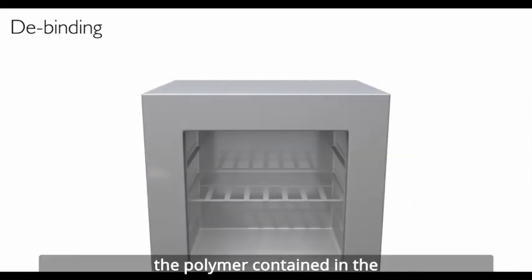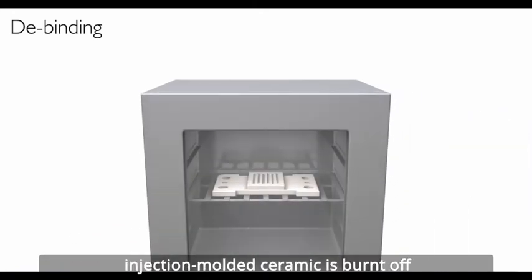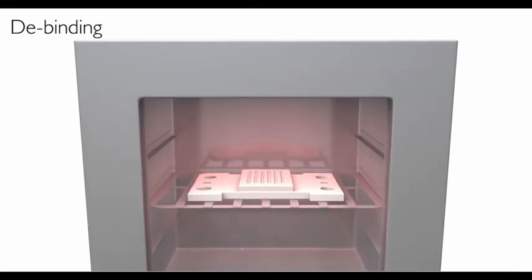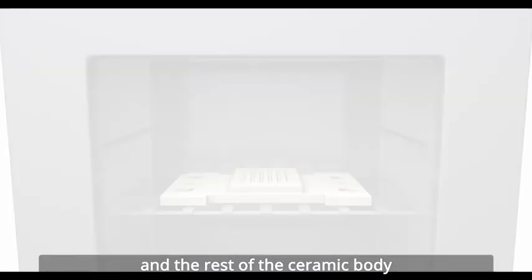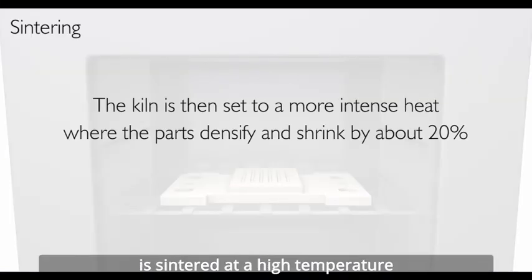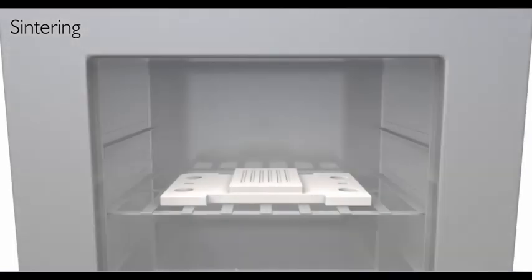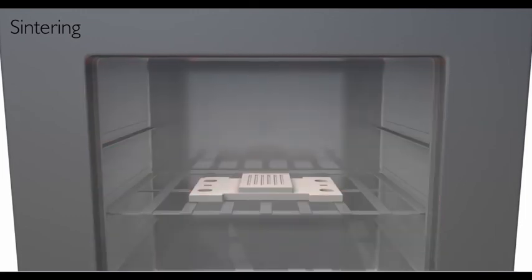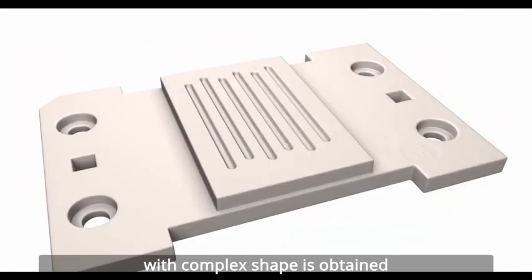The polymer, such as the binder contained in the injection molded ceramic, is burned off. And finally, the rest of the ceramic body is sintered under a high temperature. When it's taken out of the furnace, the designed ceramic part with complex shape is obtained.